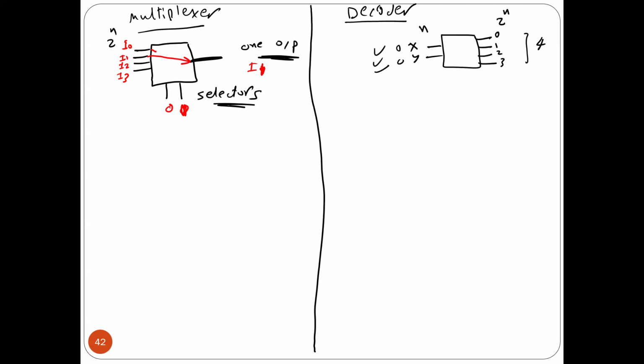It's like you have a switch, for sure, an imaginary switch. In reality, all of these are gates, but what it does is like selecting. So here, the output should equal whatever I have here. What does equal mean? It's very easy. If the input is 0, the output is equal to 0. If I connect the output to I1, then whatever you have in I1, 0 or 1, you will see it here.